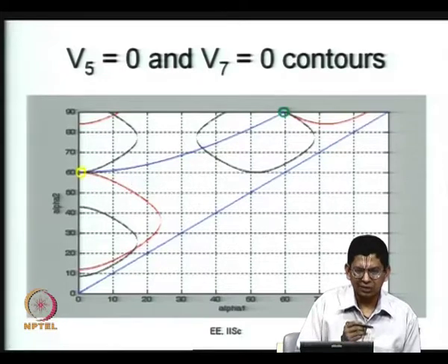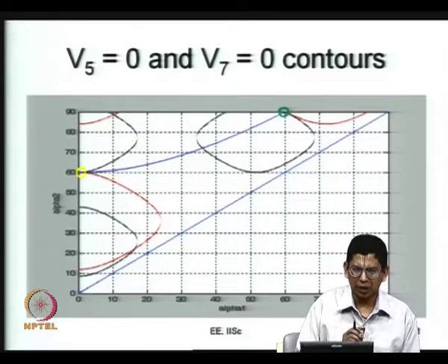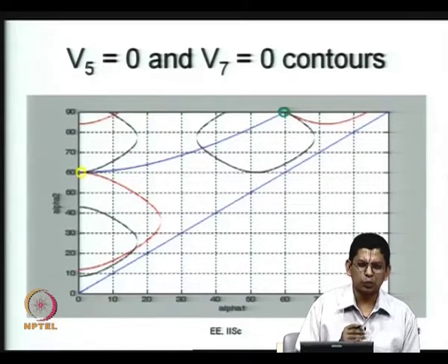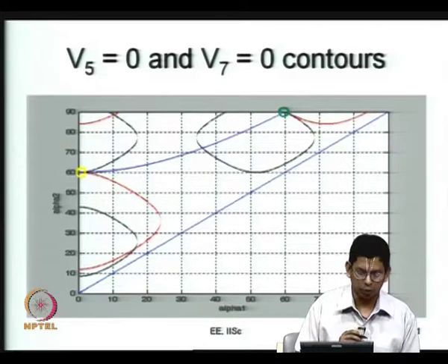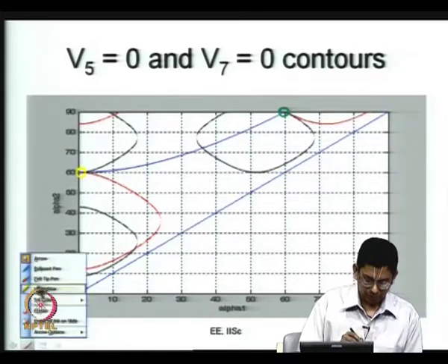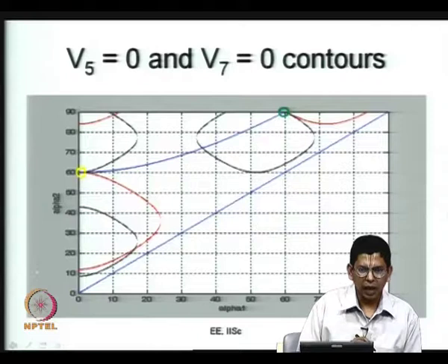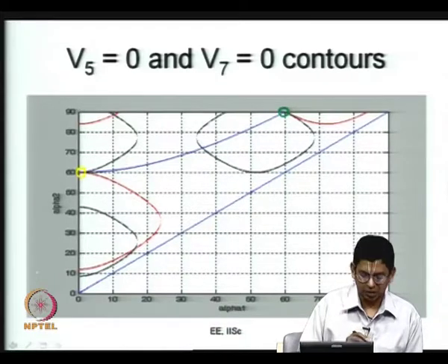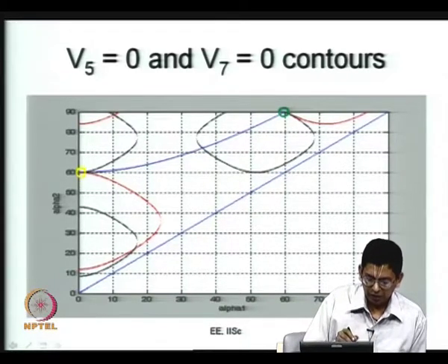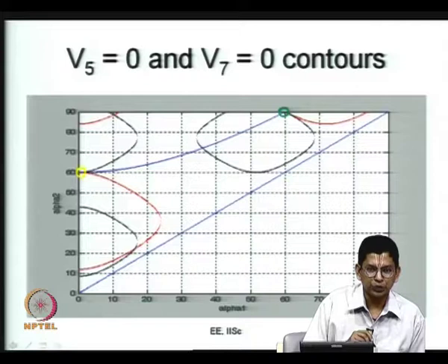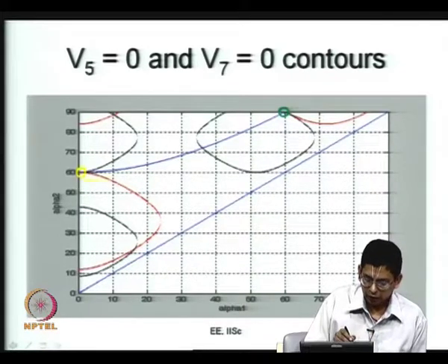Now, let me say V1 equal to 0 is not a point at which you would operate. We are trying to understand V1 equal to 0 mainly to understand the issues related to V1 equal to say 2% or 3%, a small amount of voltage. Now, let me go back to this. I want to use something like V1 equal to 2% or 3%. So, if I were here, what I would choose, that curve can really be going somewhere like this.